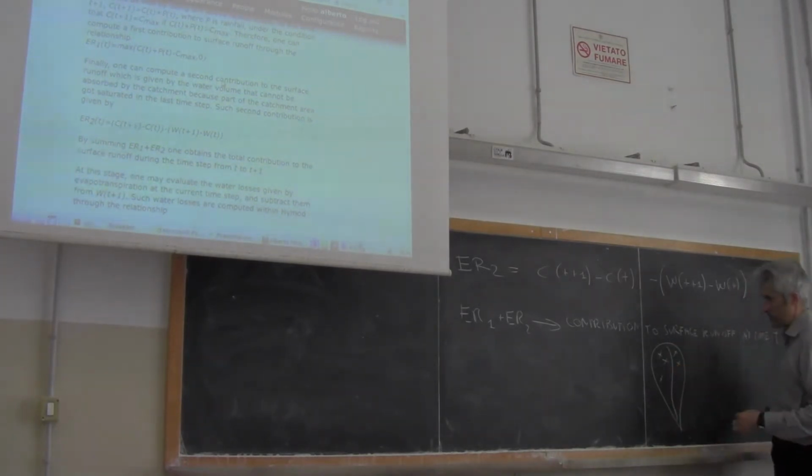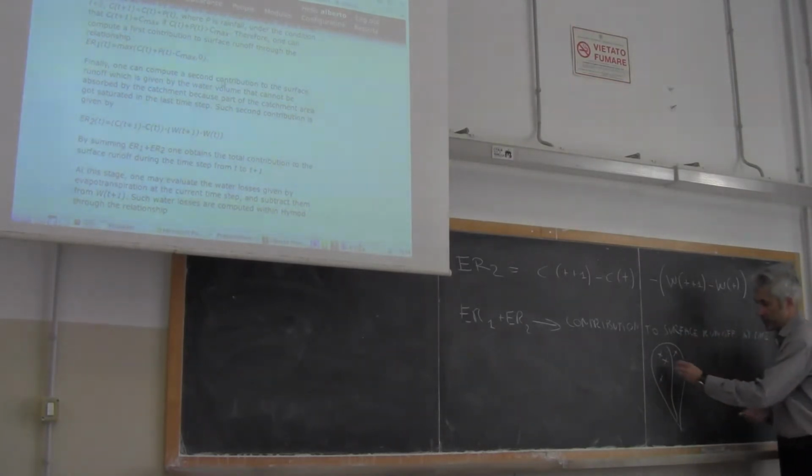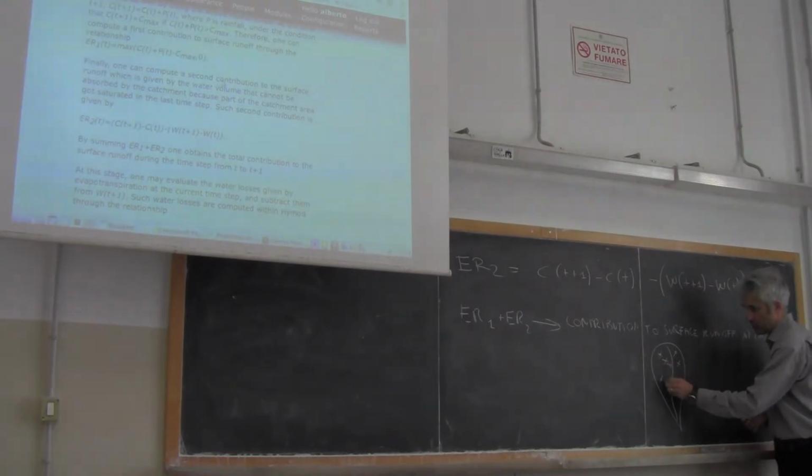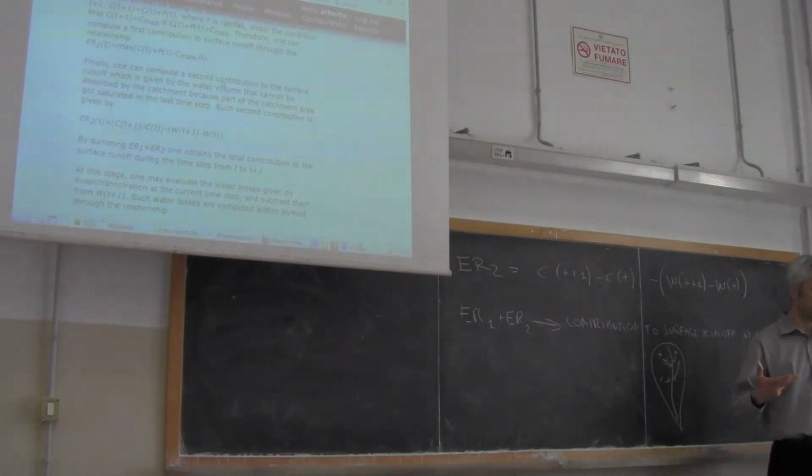This water is surface runoff produced in a distributed fashion over the catchment, and then this water has to go to the river. If the catchment is completely saturated, because we got to a Ct that is higher than Cmax, water is produced everywhere, but still has to travel to reach the river. So we need to take into account this travel time.